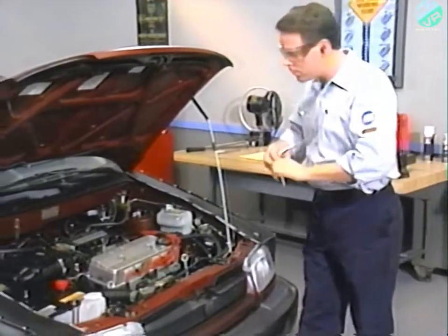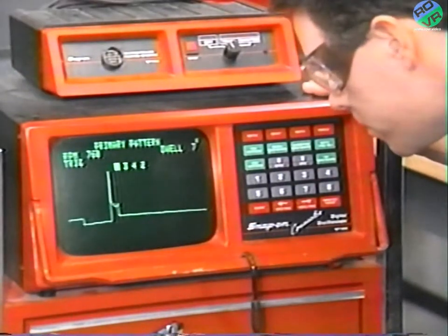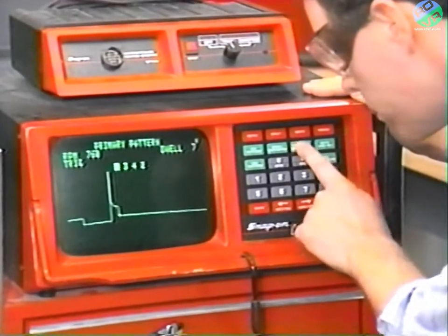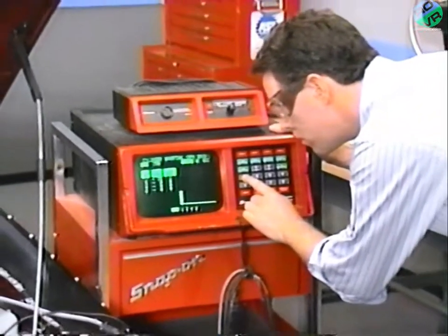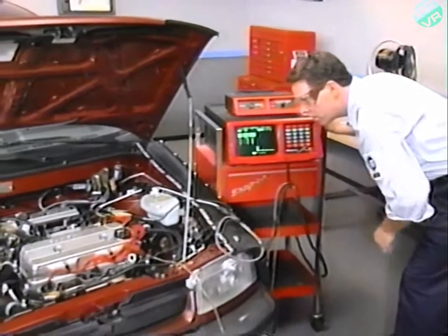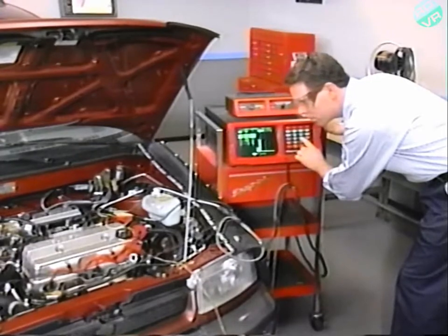Using an engine stethoscope can help pinpoint the problem without having to disassemble the engine. If you believe the engine knock is the result of piston slap, isolate each piston in turn by electronically canceling each cylinder using an engine analyzer. Caution, don't do this for long, as it will heat up the catalytic converter. If the noise goes away, you've located the cylinder that's producing the engine knock. Based on the results of the test, you can then decide whether the engine will require disassembly or not.